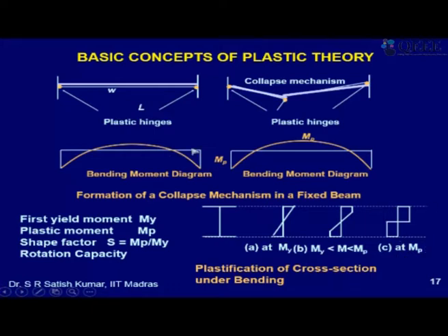So it will reach that, and then after this it cannot take any further bending moment because it has reached its full plastic moment. So what will happen is, we say that it has become like a plastic hinge. We lump the plasticity at a point and we say that this hinge will now go on rotating at constant MP. Okay, so that is what we find here. We have put orange dots here. So this beam has become like, I would say, a simply supported beam with equal end moments MP.